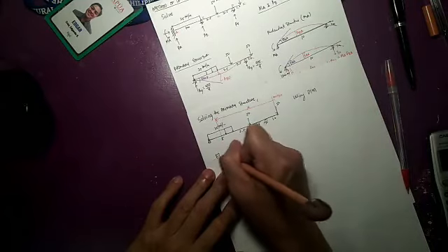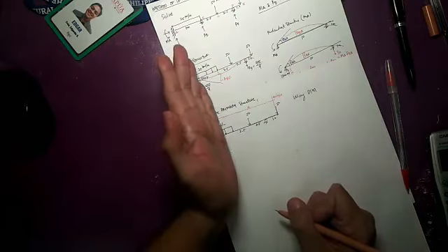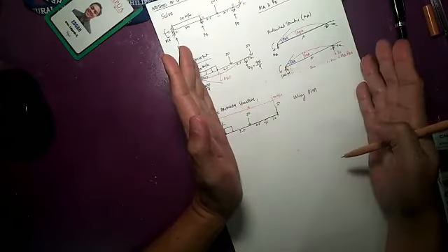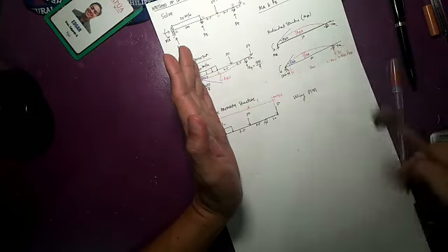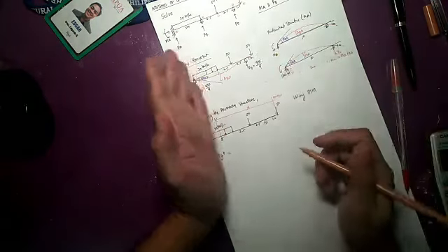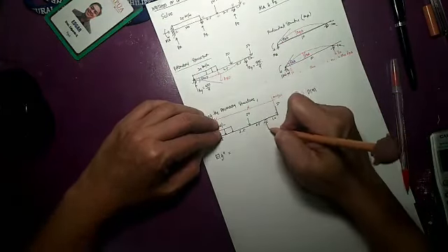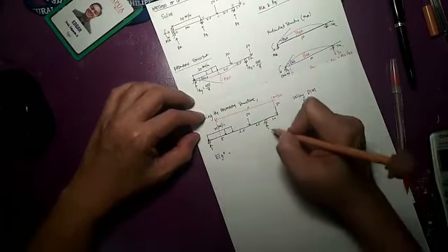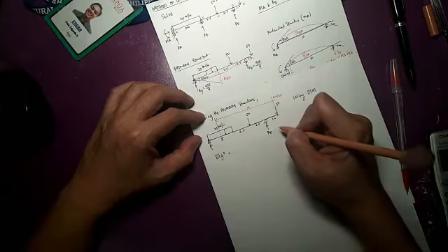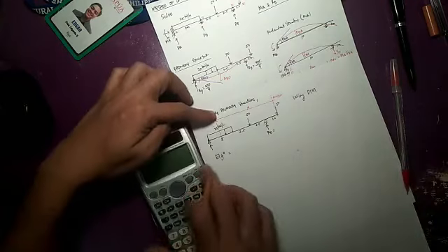So let's say EI y double prime is the moment equation. If we cut the section of the beam here and I consider the right segment, by my sign convention clockwise is negative, counterclockwise is positive. First we have to solve for the reactions. We need the reaction here and the reaction there. So this is the reaction at point D.